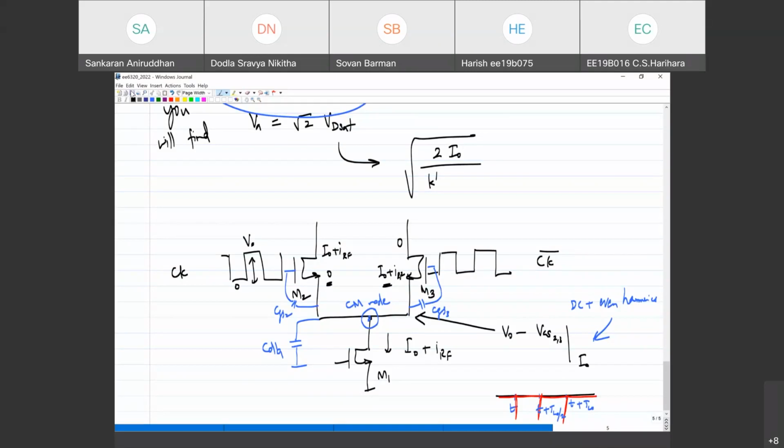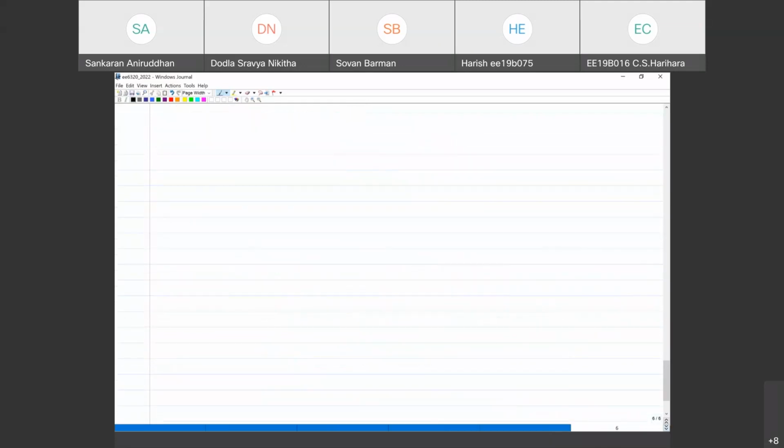No. In the case of the active mixer, you are basically adding currents, not voltages, at high impedance nodes. You will not see that effect. In the case of the passive mixer, you have switches, and for some period of time, the input can be transparent to the output. That will not happen in the case of active mixers. So if you take active mixers and try to combine single balanced versus double balanced, what is coming out is a current, first of all, not a voltage, right?